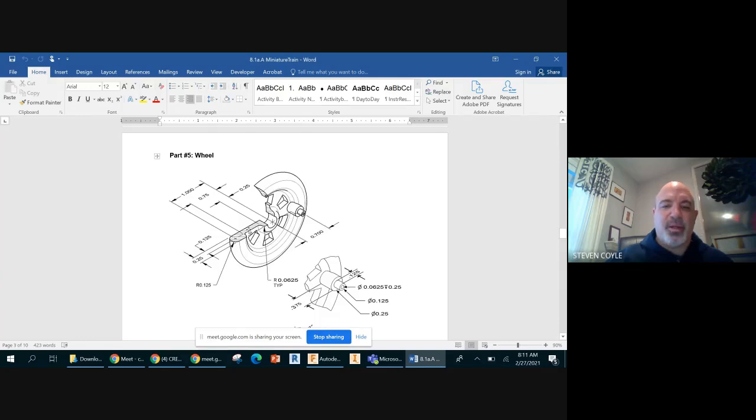Right now I know I'm making a round object, so I'm going to use my Revolve tool. We have to have a part here where the axle peg is going to go. So I want to start a 2D sketch, and I'm just going to draw an axis here, which is going to reference that space, and I want to figure out how far this is going to be away from each other.